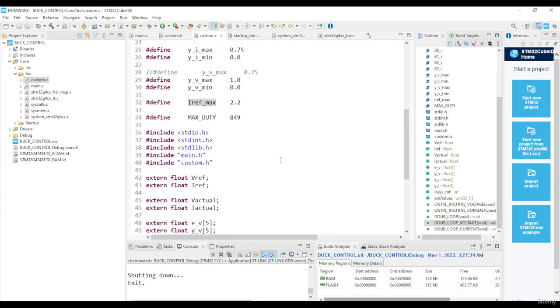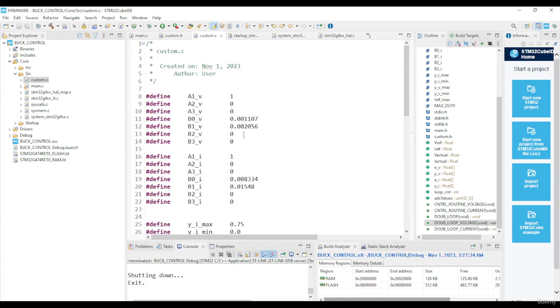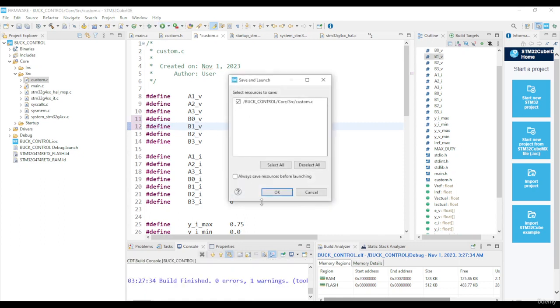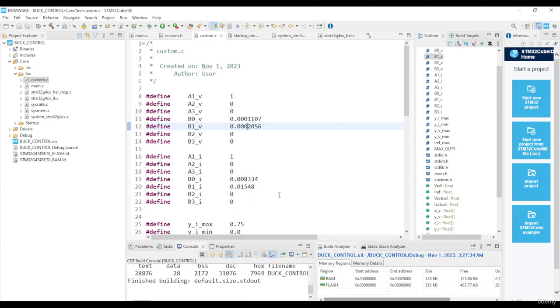And also, you might want to fiddle around with these coefficients a bit, because they are primed for single loop control, not double loop control. As you can see there, it was fluctuating just a little bit, but you can modify these coefficients to make it much smoother. Specifically, the voltage one, you don't want it changing as much. If I show that in this case, if you want it a lot smoother, you want the voltage to be a lot more stable.